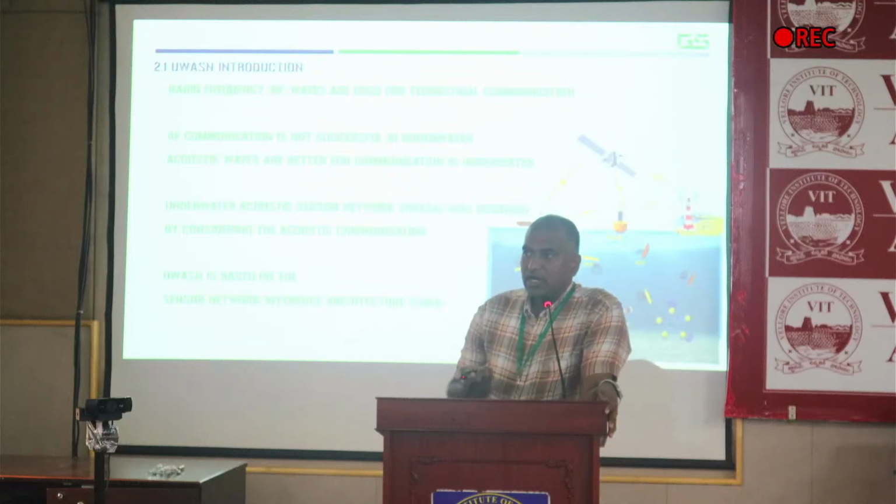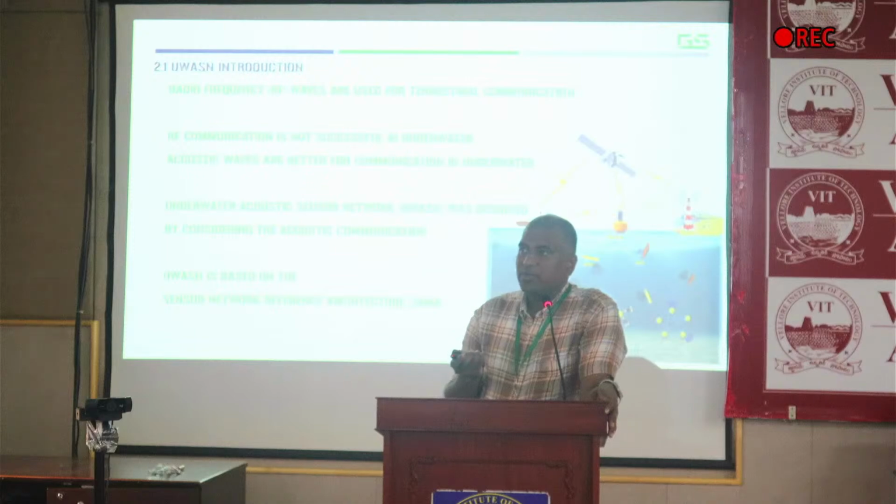So these underwater nodes use acoustic communication, whereas to transfer this data to the terrestrial networks, we use radio frequency communication. For transferring data from underwater to terrestrial, these gateways are helpful. The gateway modems do the major protocol translation. The gateways can be ships or underwater buoys. So these gateways are installed here.